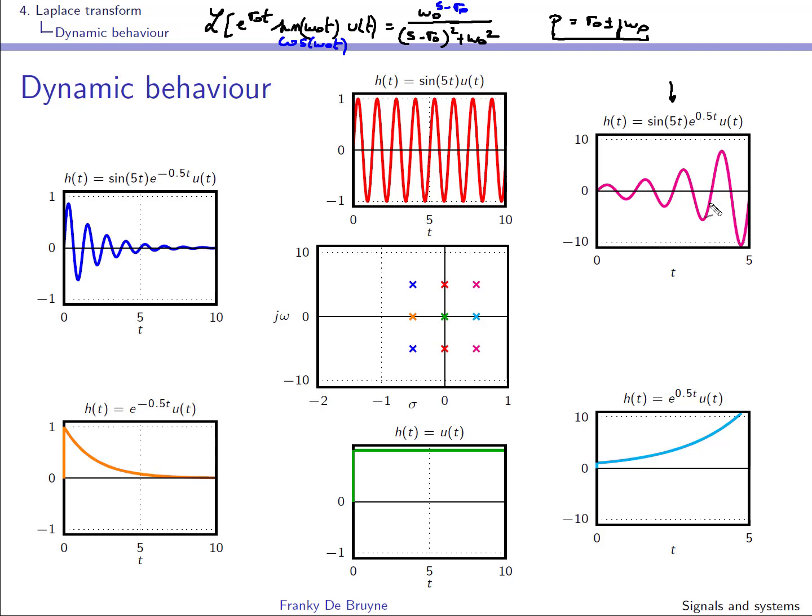It's an unstable impulse response, and it's an exponential that is modulated either by a sine or a cosine. Knowing if it's a sine or a cosine will not depend on the poles, but will depend on the numerator, so it will depend actually on the zeros. If you have complex conjugate poles on the imaginary axis, this means that sigma 0 is equal to 0.